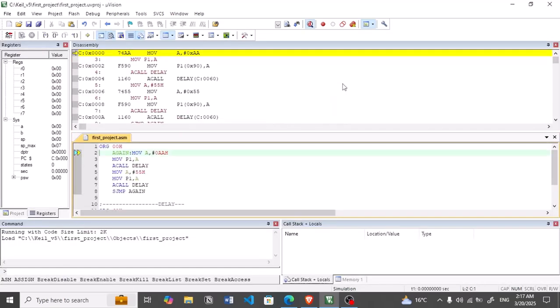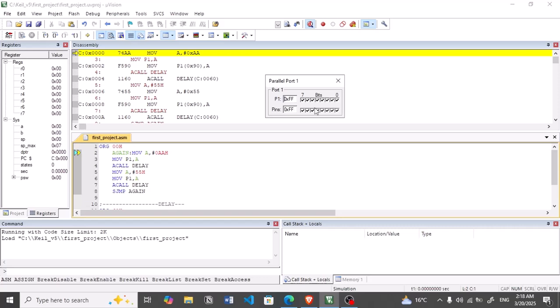So this is my program, and in order to run it, I have ports here, so let me move to peripherals. Here I have different peripherals, like port 0, port 1, port 2, port 3, and timers as well, but now I have to go to port 1. This is port 1, and the default value for port 1 is FF, which I have told you is because all the values written here are 1s on all the pins, as it behaves like an input port.